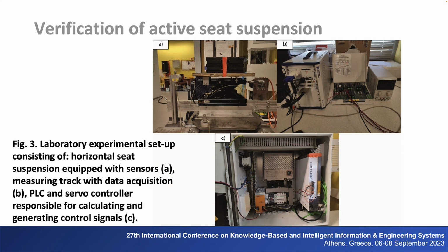Parameters of the SMC controller must be declared as well, therefore the η is set to 0.05 which results in satisfactorily fast reaching of the sliding phase. The other control parameters are adopted with the following values, K equals 10 and CS equals 1. The simulation time is fixed to 180 s duration. To solve differential equations included in the model, the Bogacki-Shampine algorithm is employed at sampling time of 1 millisecond. The excitation signal used during simulations and experimental tests is called WN2 from previous work which demonstrates spectral properties like the white noise signal in frequency range 0.5 to 10 Hz.